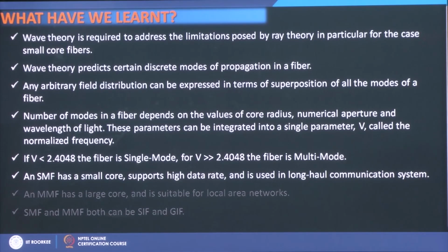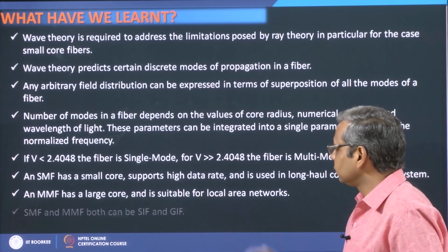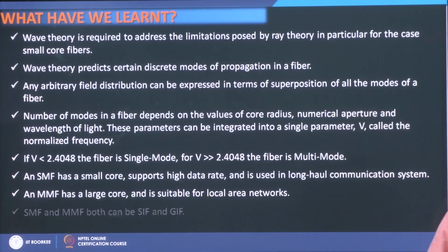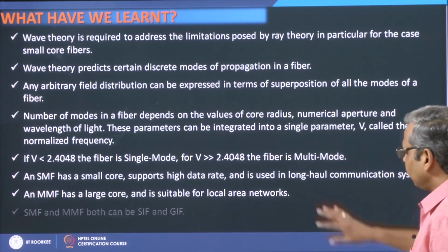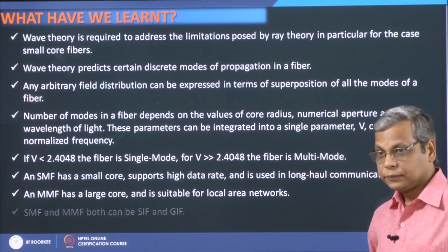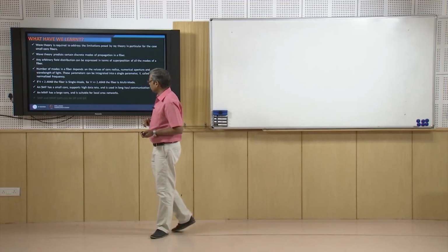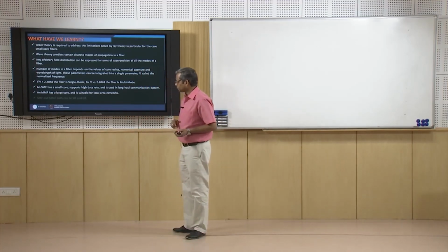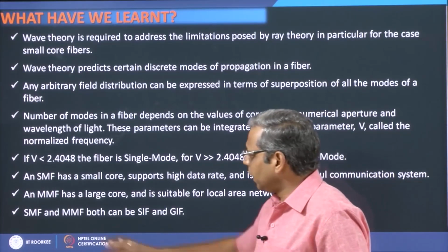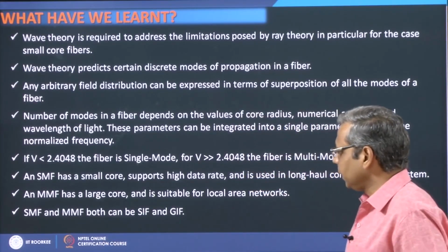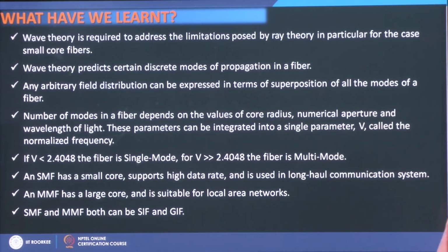it is used in long haul telecommunication systems, while a multimode fiber has a large core and it is suitable only for local area networks, apart from other applications other than telecom applications. And single mode fiber and multimode fiber both can be step index fibers or graded index fibers.